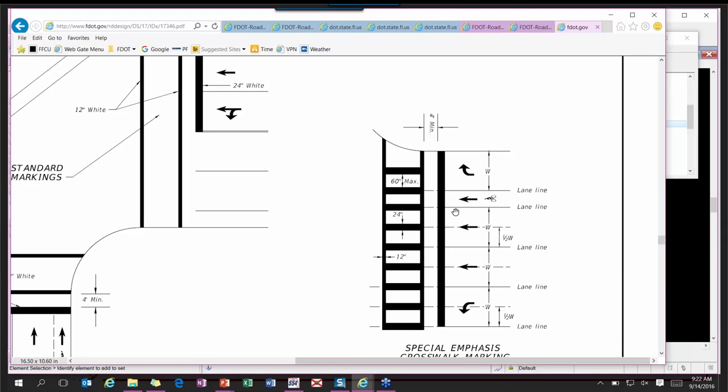And once I have the lane lines in, then I've got to place another one at the center of that lane. You don't want to put them in where the tire tracks are going to be. You want to make sure that they're in the center. Okay, so this will be a two-step process. We'll get the lane line markings in, then we'll go in and copy parallel. So this is really, for this part, it's pretty much just using MicroStation commands.